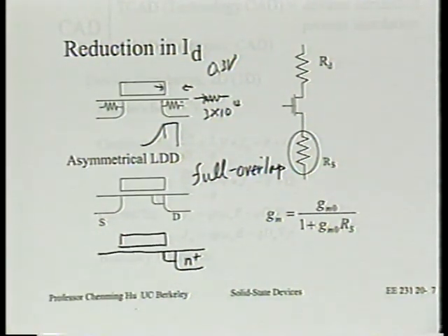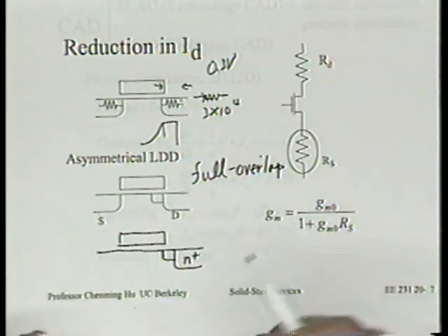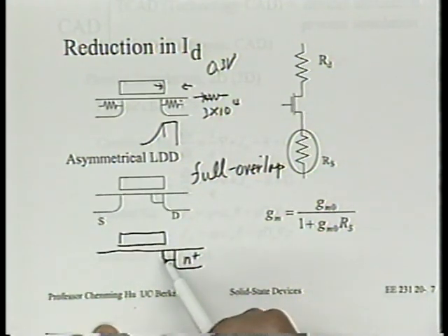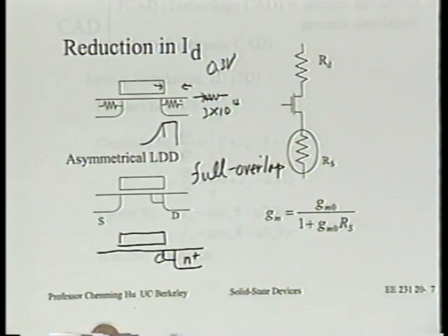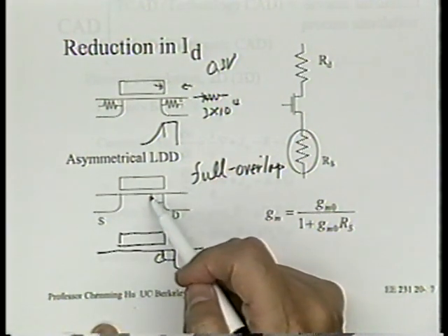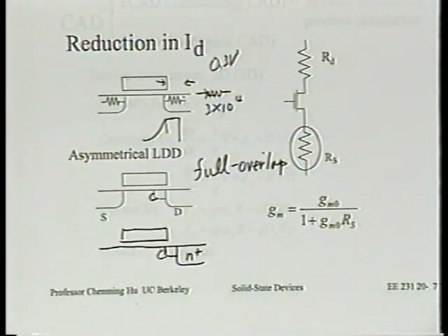But when you consider the super halo doping, it looks like the halo doping is inside the channel, while the LDD structure, the source drain extension, is just outside. They both are. Again, this is all hand drawing. An easy way to draw is this way: say the halo will be like that. But in reality, the halo can be like this as well. That's not a problem.